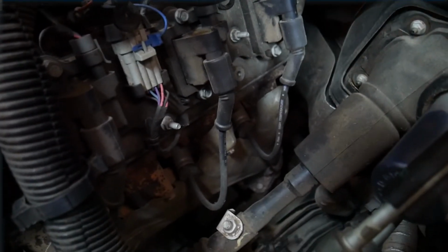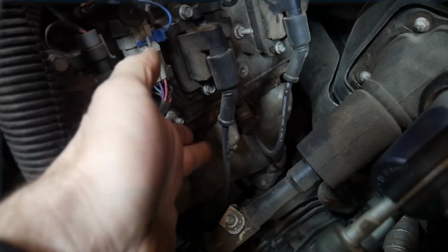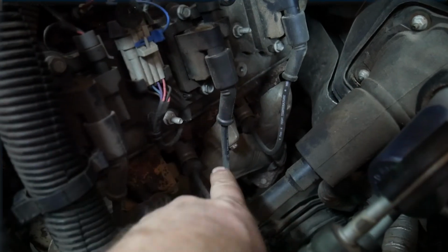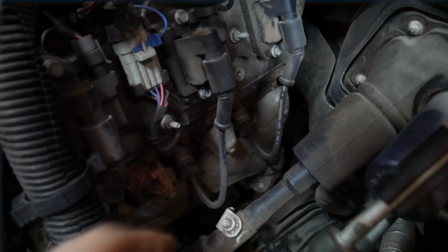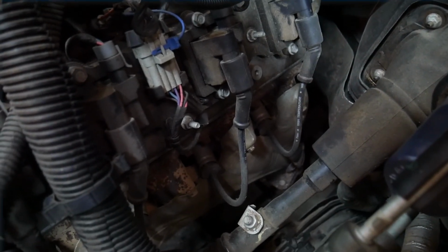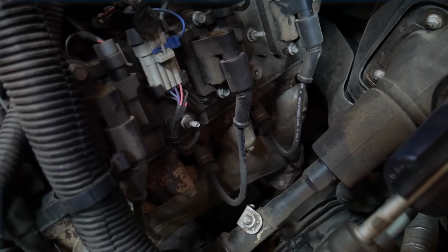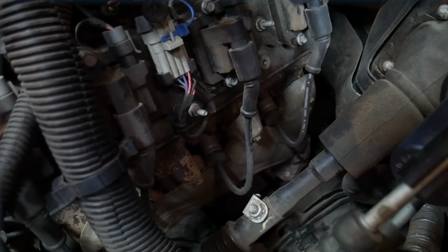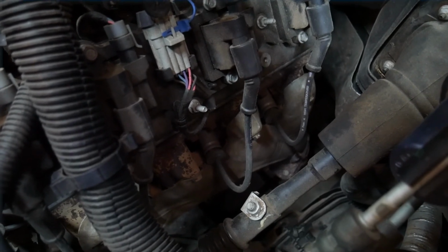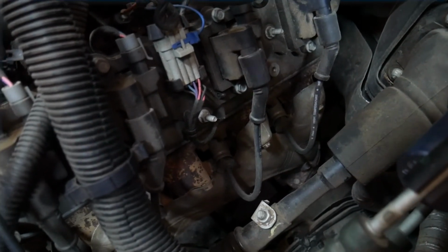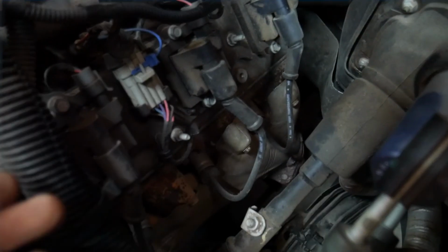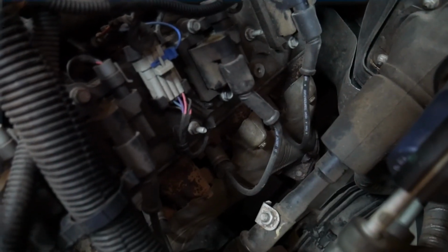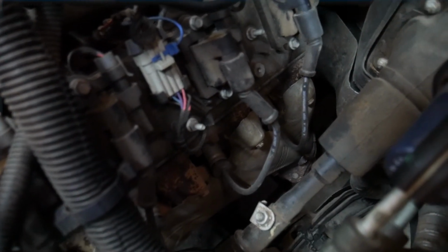Early on, I did notice that it has the wrong plug wires. It has the longer plug wires installed. And this one does rub this lock tab on the steering shaft. And I checked to make sure it wasn't arcing, because I thought, well, maybe it's just arcing, sending a spark through there, and it's freaking out the modules and the communication lines. That's not the case. Now, if you do have these longer wires, you can normally just rotate the boot up like that. It'll shorten that wire about 1/4 inch and keep it away from the steering shaft.